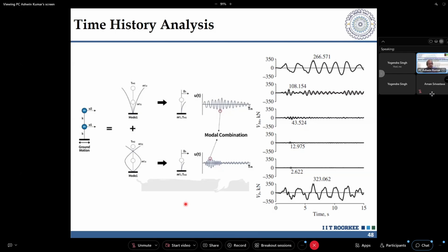If it is a bit complicated, let's say a curved bridge, wherein a grillage model might be better than a single frame model, you will easily understand which one is better. When I said a curved bridge, you yourself might have thought, the frame model might be very approximate for the deck analysis, and grillage might be the better one. But I say no, even beyond grillage you can do finite element modeling through meshing, etc. That might be a better analysis to get the final answer.